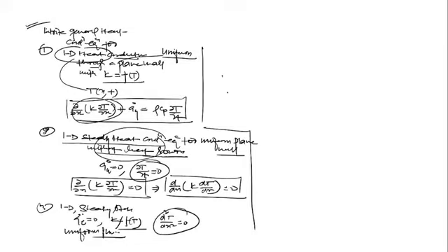Let's say if the condition is like this, these surfaces are insulated, no heat transfer in this direction. That's why I'm talking only about temperature variation in x direction here. Only temperature is going to vary in x. This is x direction here. Here temperature is T1 and here temperature is T2, the end of the rod, but area is going to vary.